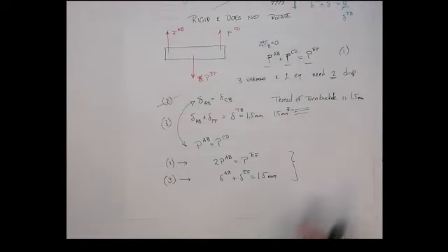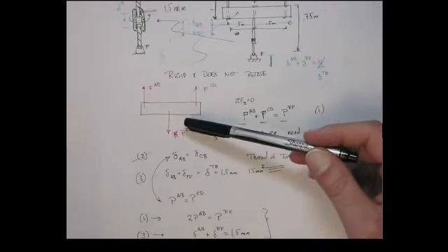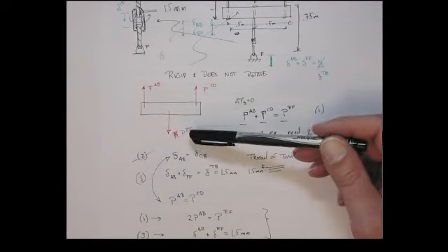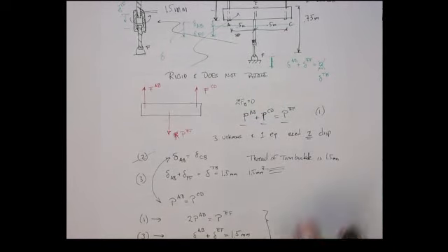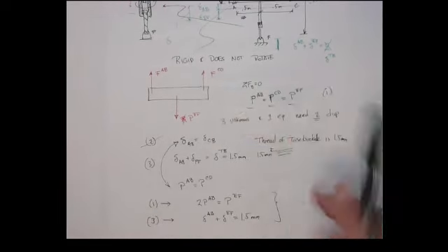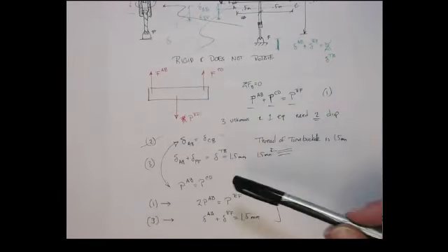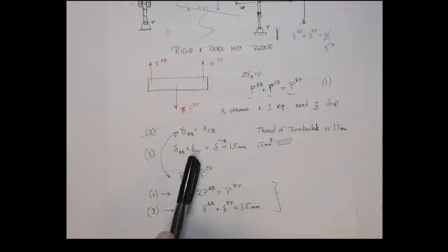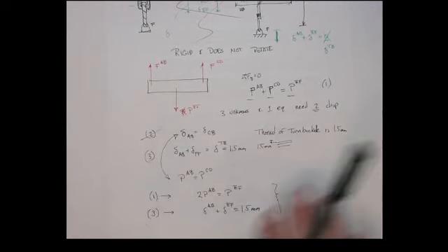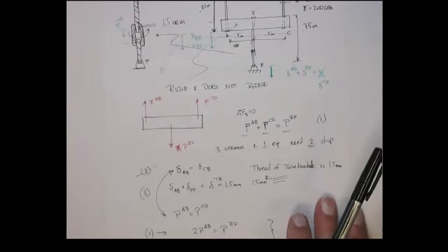In this situation, it's always good to assume your internal reaction forces, well, I shouldn't say that. It's really essential in this problem to assume that your internal reaction forces are all positive. And like I always say, you should always assume that the reaction forces internally are positive in tension, all right? Or when we talk about bending and torsion, positive in those senses. Why? Because the correct value of P will give me a delta that's positive when it elongates. Now, obviously here, these guys are going to be probably of a different sign. I think. Well, no, maybe not. No, actually, they'll be the same sign.